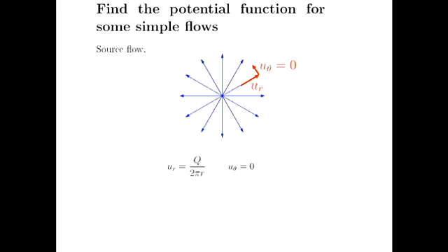And we also showed, when we derived that equation for a source, that if I consider a circular control volume and I apply conservation of mass, I know that the radial component of velocity UR is just a function of the inverse of that radial position. It's just given by Q on 2 pi R. This is exactly the same as the previous derivation we did. That's just through a conservation of mass.